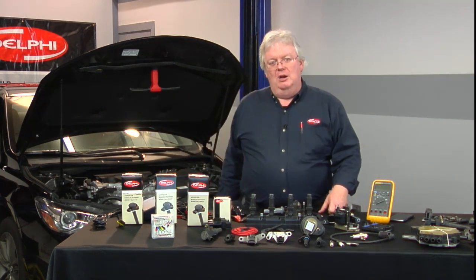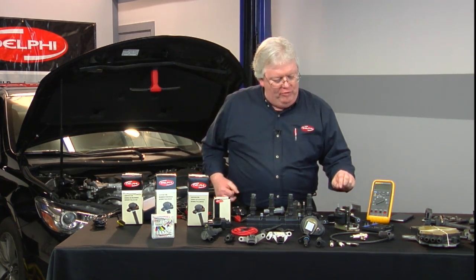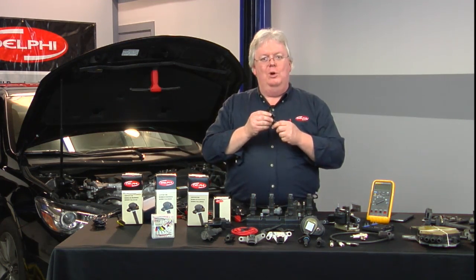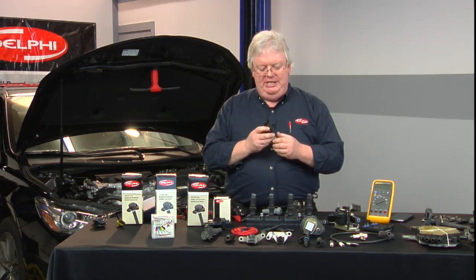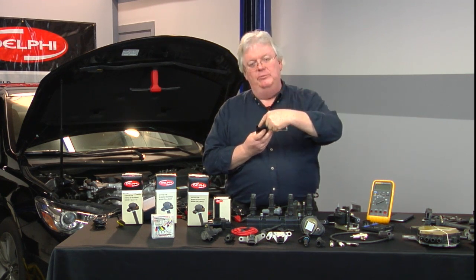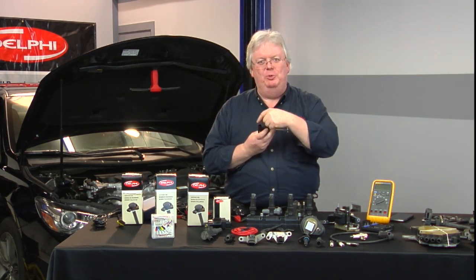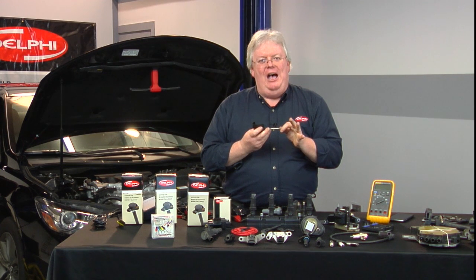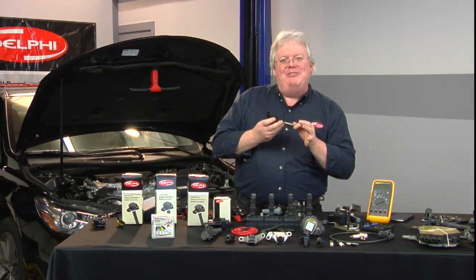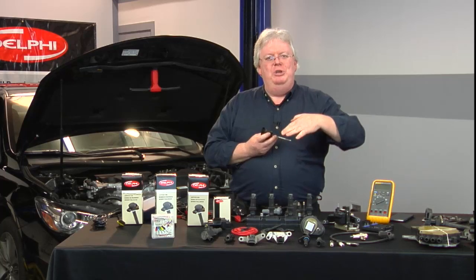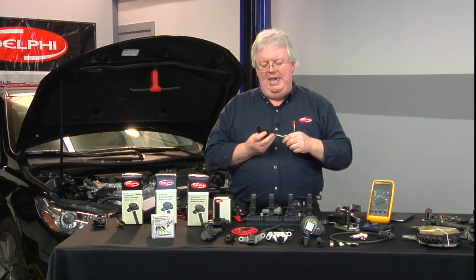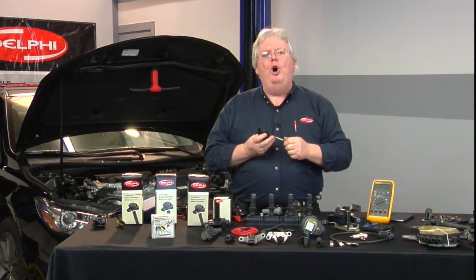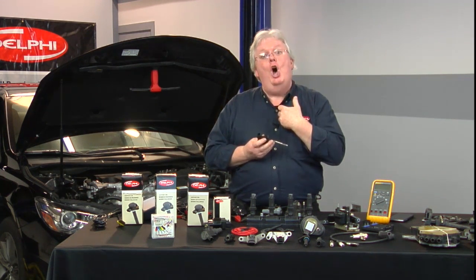On Coil-On-Plug, is the primary usually isolated from the secondary circuit? On the 3 and 4 wire Coil-On-Plugs, yes. On the 2-wire, like this Ford or a Dodge, no. Typically, you will see a connection between here and both of these wires. Within 0.6 of a difference between each other, you'll never notice it because 5,000.6 versus 5,000 ohms is indistinguishable when you get that high a level with your ohm meters. It'll just say 5K between either one of these terminals and here on most all, if I'm not mistaken, all the 2-wire coils.